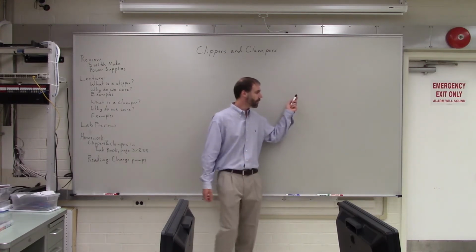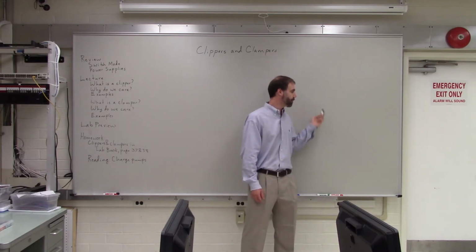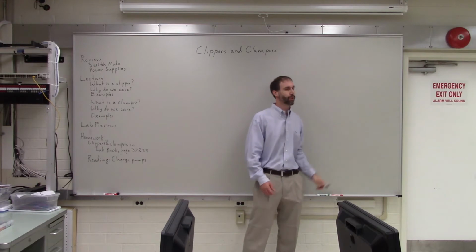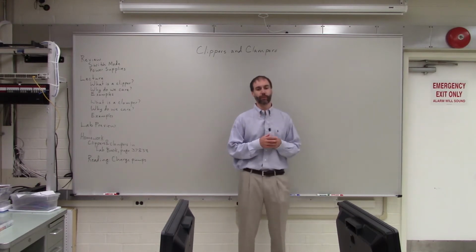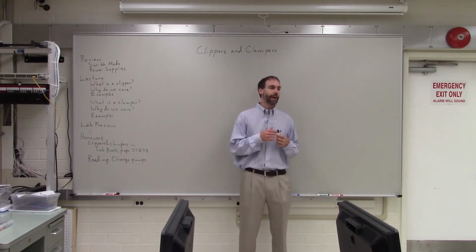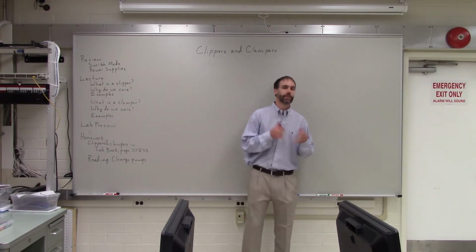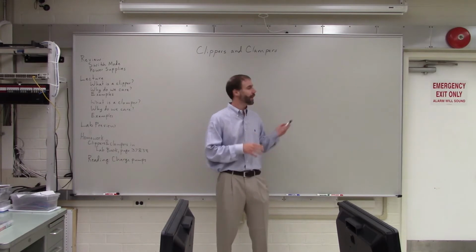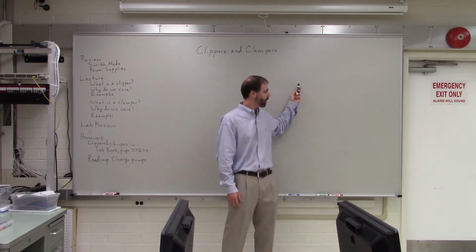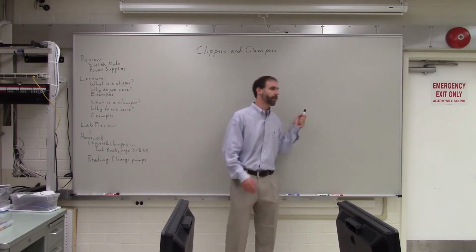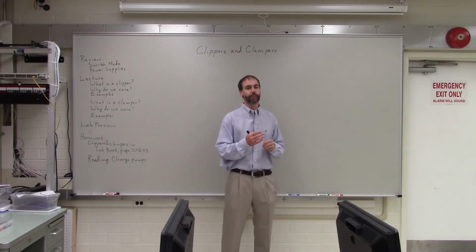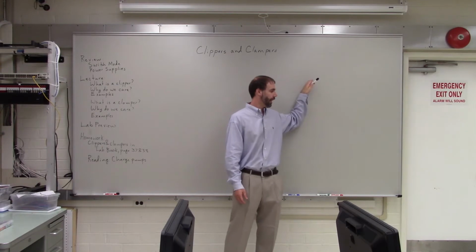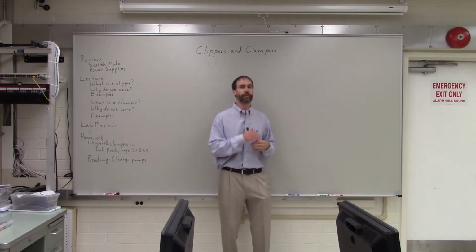So the more complicated switch mode power supplies that were in that video had that whole transformer arrangement, and they could create several different output voltages. In lab, we built a simpler version of a switch mode power supply. The one we built in the lab was called a buck regulator, or a switching regulator. It would take a DC voltage and then lower it to another DC voltage.